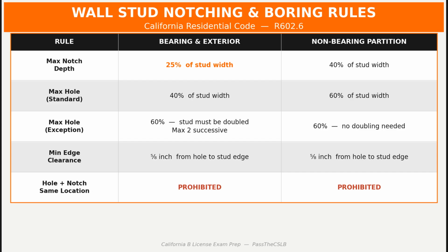And the trigger, 50%, roof rafters, same fractions, same logic. Solid sawn roof rafters follow California Residential Code R802.7 and R802.7.1, and the rules are structurally identical to floor joists. That is not a coincidence.